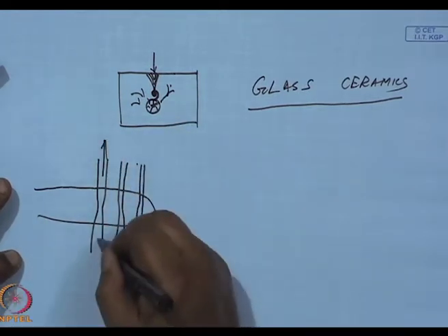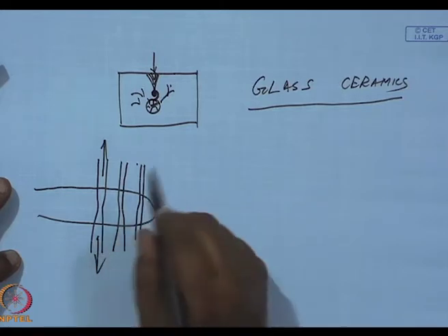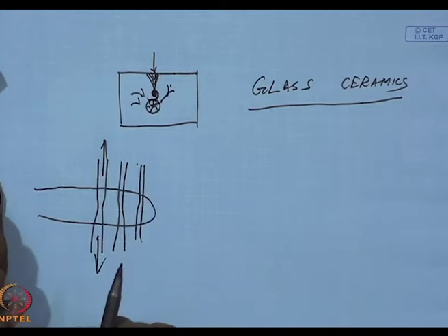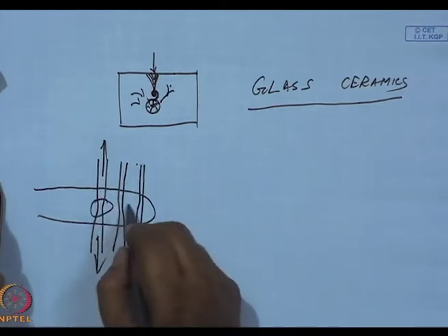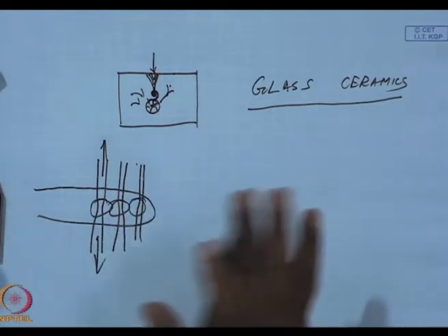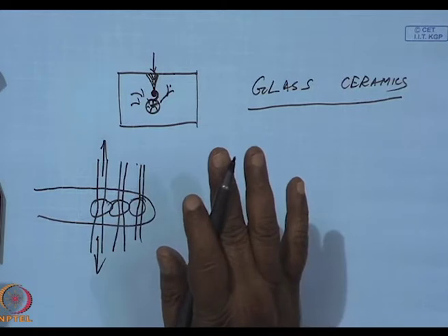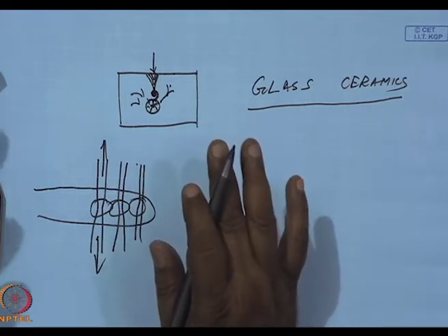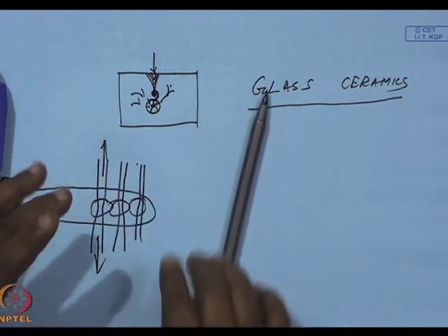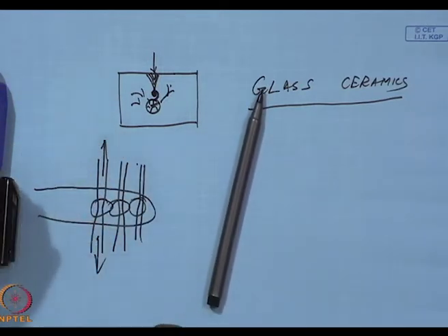These will also have to be pulled out. The crack would stress these fibers, forcing them to undergo necking. Now, here please understand, I have drawn on a very exaggerated scale. So, as the crack tries to proceed, the fibers are also elongated,